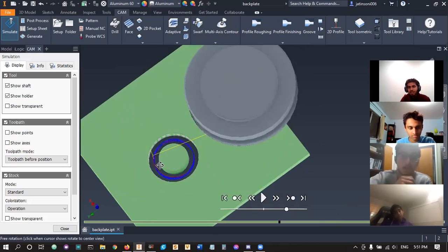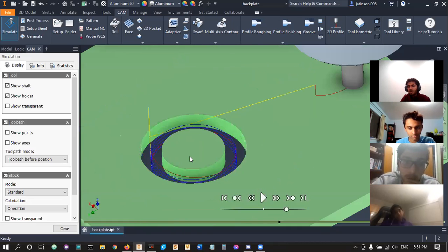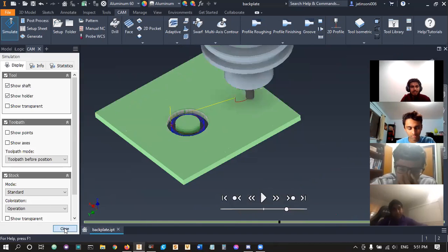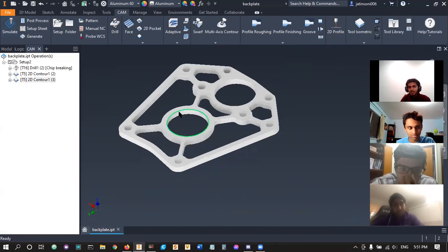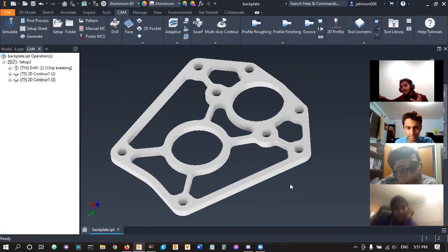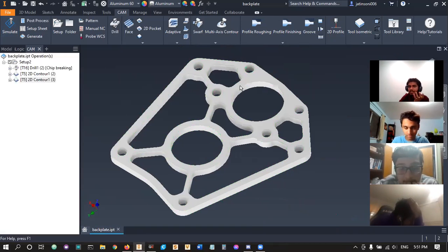And that's a free floating piece of aluminum without anything holding it down, right? And remember, the end mill is spinning at like 15,000 RPM, 12,000 RPM. So when that thing touches that free floating piece of aluminum, it flies out. So that's why we don't just do an outline cut. And if you ever do have to do it, is if there's a really big pocket and it's going to take forever to cut everything out of the way, then we just put screw holes in the middle so that it doesn't fly around.